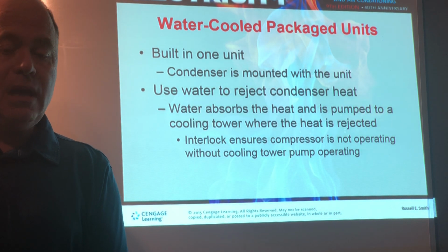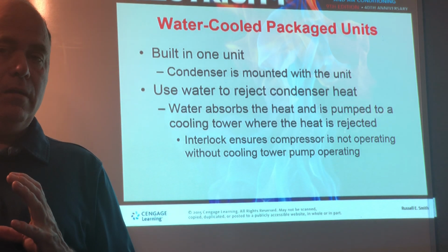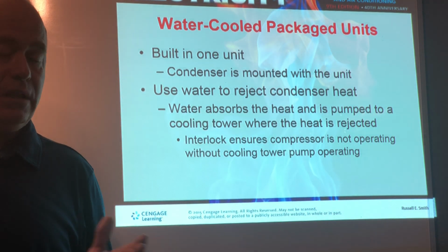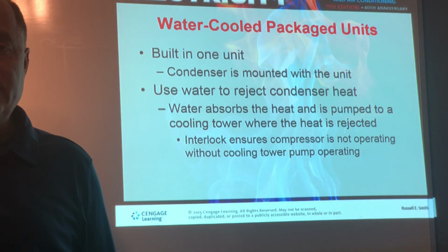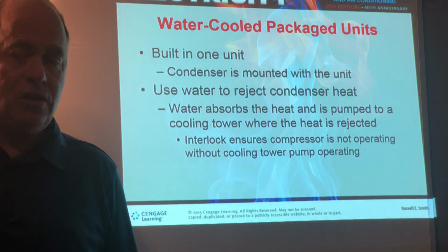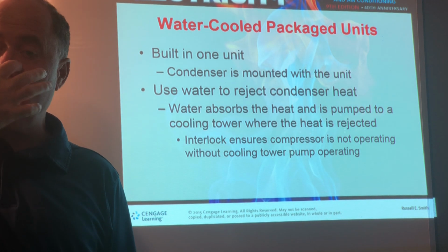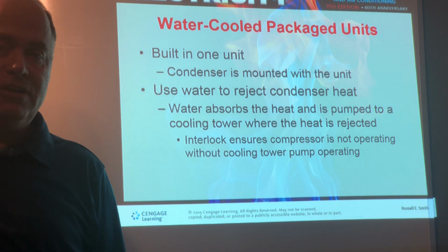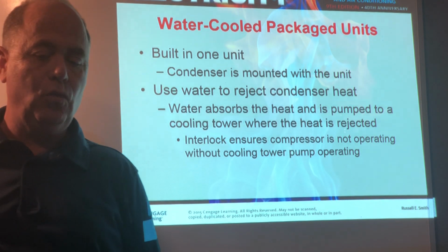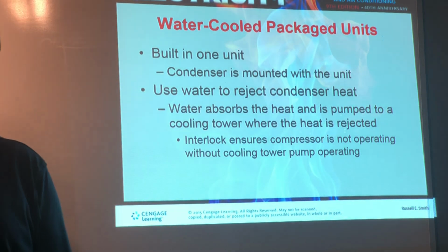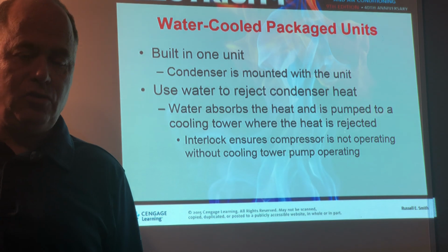Again, we talked about water-cooled package units where they can be much smaller than what you think, let's say, a 5-ton package unit would be, because you don't need to have all this extra space because they're more efficient and the water takes the heat away, and then you have a separate cooling tower that actually evaporates the water and gets rid of the heat. So you will need to have a condenser water pump that serves these water-cooled package units.